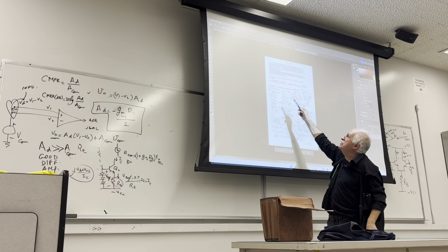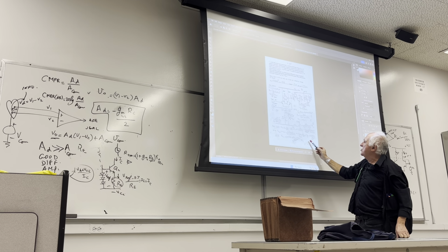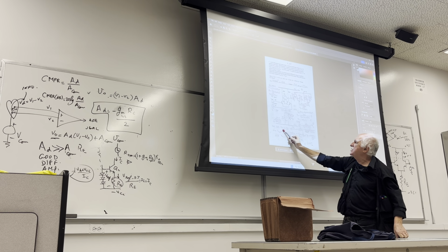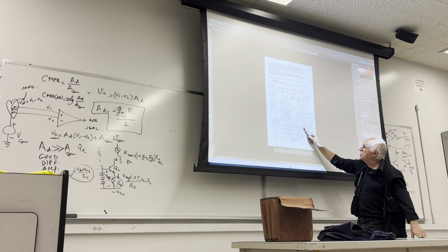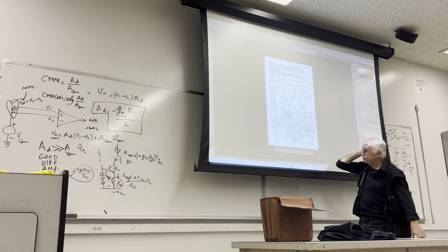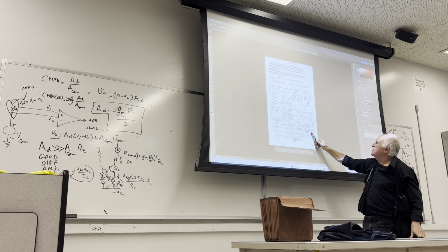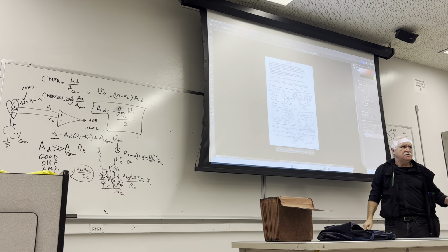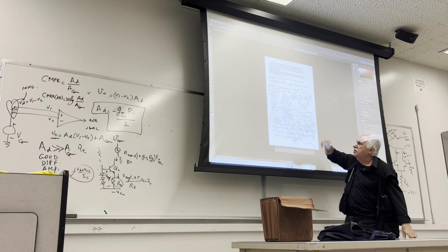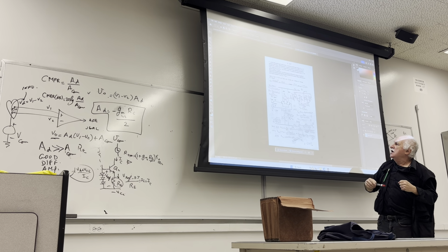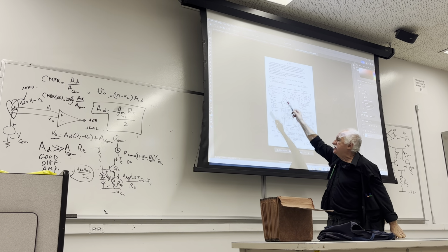But let us look at the common mode voltage gain, ACOM. ACOM of that one, utilize this formula here. That one is an approximation formula, which is an approximation to that exact equation. We calculate that, and it turns out to be 5 milli. The gain ACOM is 5 milli, as opposed to 13.5. Then what is the CMRR? It's got to be the ratio of the 13.5 to that 5 milli.